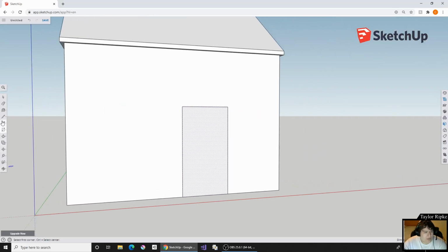And I'm going to actually create an offset. So let's go ahead and use the push-pull tool offset on the left-hand side of our screen one more time. If you notice, if we do the offset on this, we're going to have an unfortunate thing happen. It's going to extend beyond the bounds of that, which is not something that we want it to do. Rather, we want to have it based on these lines. So if we hold down Shift and click these lines, we just want to select the door frame, essentially. We want to make sure not to get this thing here.